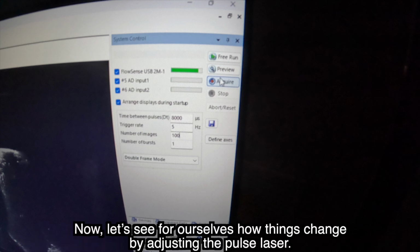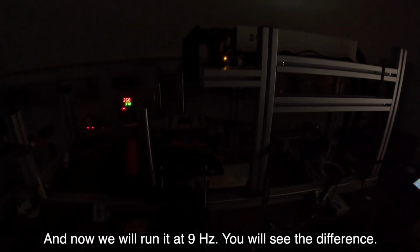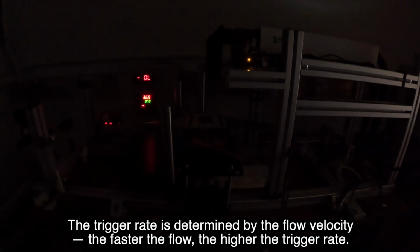Now, let's see for ourselves how things change by adjusting the pulse laser. First, let's run it at 5 Hz. So this is 5 Hz. And now we will run it at 9 Hz. You will see the difference. The trigger rate is determined by the flow velocity. The faster the flow, the higher the trigger rate.